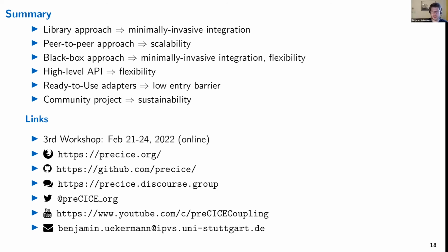You can do overlapping domains. For preCICE, no problem at all, right? You just have to give a different domain to preCICE, a different mesh. Our adapters currently do not all support this yet, but this could be extended rather easily in the adapters, so that the adapter would do a volume coupling, but only on parts of the domain, a small layer of cells close to the boundary. So it is possible, but needs a little bit of work.